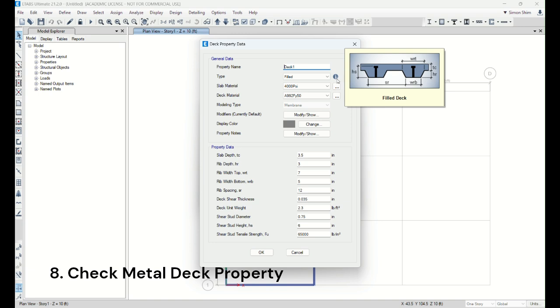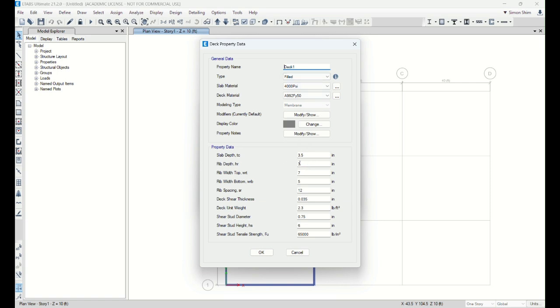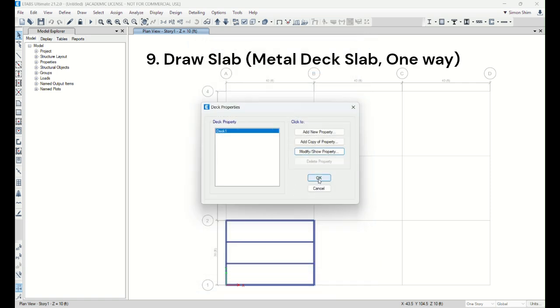Because in steel construction we use steel column, steel beam. We need a metal deck frame, like a formwork, but this is structural form. It's the tension forces. So this metal sheet, they just form it, right? After they place it on top of the beam, they weld it using some shear studs, and then they put the concrete. It's a concrete slab, but sitting on the metal deck. That is a composite steel construction primary element. So we're gonna use a 3-inch metal deck. Default is a 3.5-inch concrete topping. So I'm gonna use this.